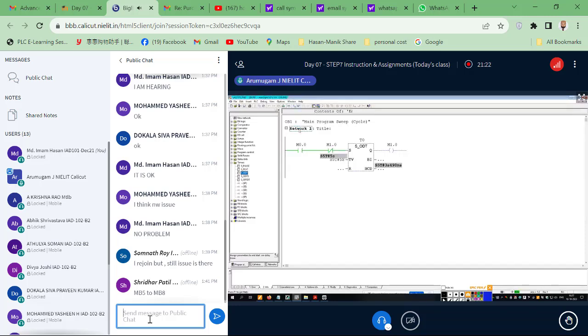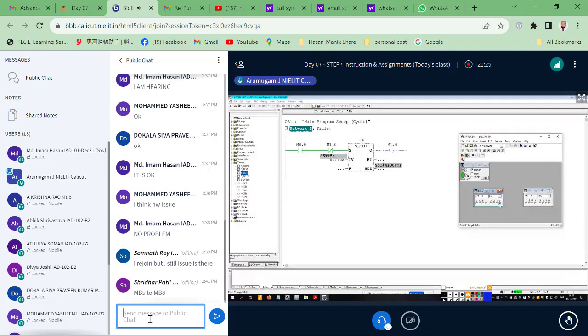You see here, be very careful, I'll show you how it's working. Now this switch is closed, right? This is a normally closed switch, and this is the normally closed switch address. Same address. Because now this is 0, this signal will go to here. If the signal goes here, the timer starts. What is the timer preset value? It's 5 seconds.